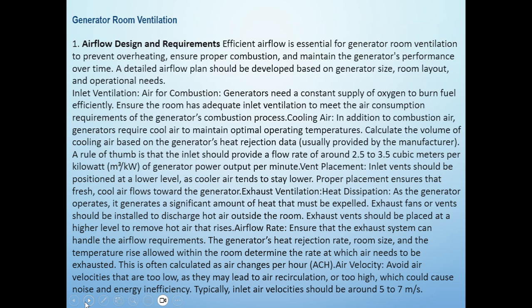And basically, the airflow design and requirements. Efficient airflow is essential for generator ventilation to prevent overheating, ensure proper combustion, and maintain the generator performance over time. A detailed airflow plan should be developed based on generator size, room layout, and operational needs. Inlet ventilation, air for combustion. Generators need a constant supply of oxygen to burn fuel efficiently. Ensure the room has adequate inlet ventilation to meet the combustion air requirements of the generator.